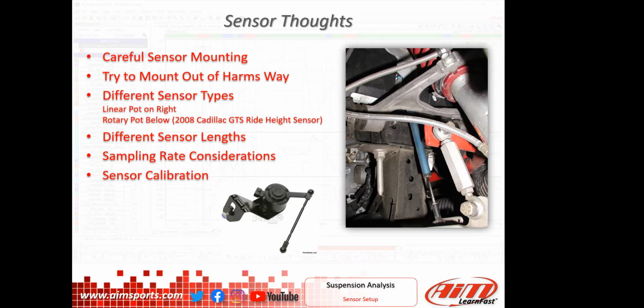I see a question from Andrew. I haven't read through it totally, but I believe it's a sampling rate consideration question. Let's talk about that for a moment. We are going to be looking at data that happens in a very big hurry. We often will have things sampled at 10 samples per second for maybe a temperature change, maybe 50 samples per second for an accelerometer, maybe 20 samples per second for a steering sensor.